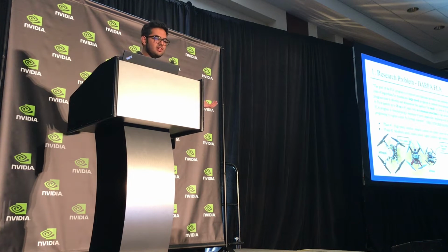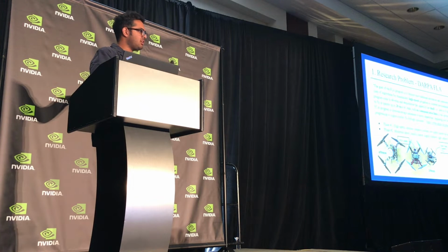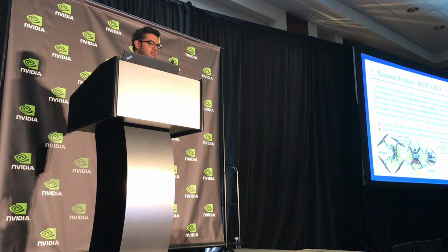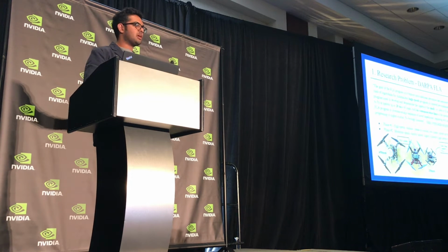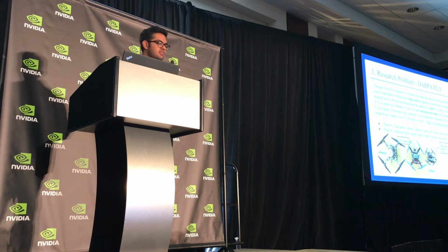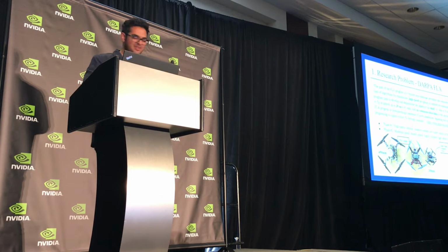Over the 3 years, we shrunk our platform down from 450 mm, which is tip-to-tip span, to 250 mm. The first platform used an Intel NUC. It had a Velodyne LiDAR. It had all the bells and whistles, but that was too big for us to fly indoors. And DARPA said you need to make it smaller and smaller and make it do what it was doing on the big platform in a smaller package. One of the first things we did was to get rid of the Intel NUC and the LiDAR. LiDARs were really expensive, and we broke a couple of them, so we'd like to not do that.